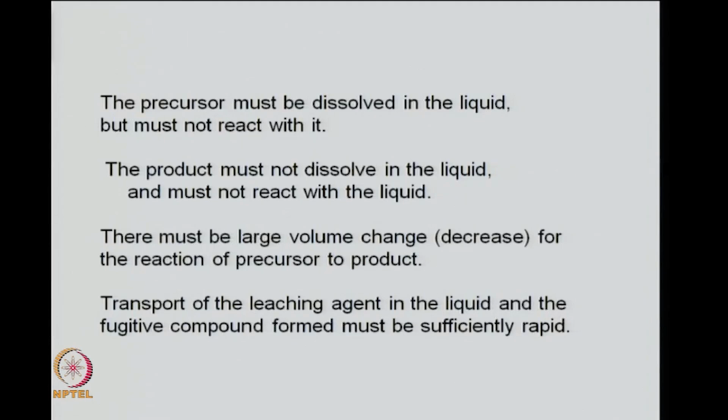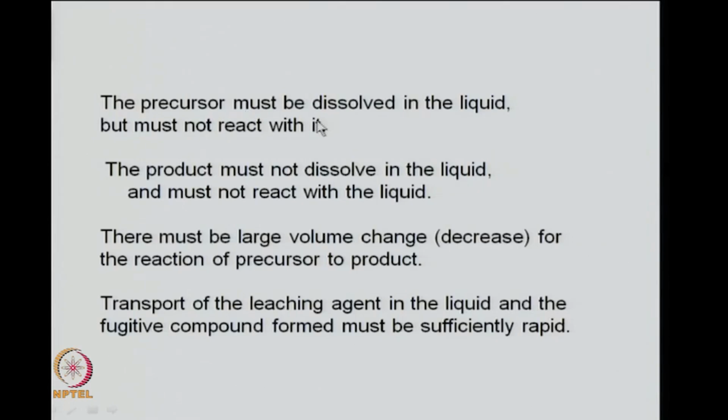In the spray pyrolysis method, certain factors need to be considered while doing the process. The precursor that you choose must be dissolved in the liquid, most of the time that is water, and must not react with it. This is one of the very important points: whatever you take as your starting reagent with which you are going to do the spray pyrolysis should not react with the liquid in which you are dissolving.